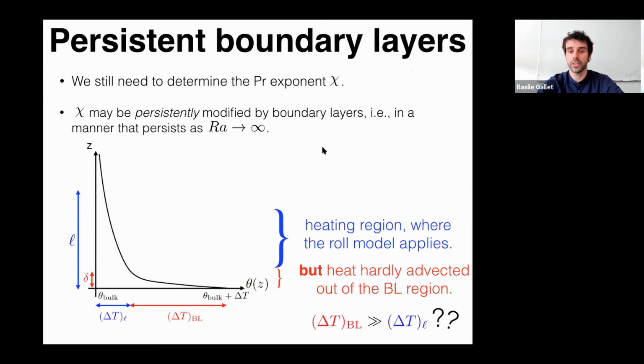However, this is still a real experimental tank, so we have a no-slip boundary condition at the bottom, and so there will be a boundary layer for the temperature field near the bottom. There will be a boundary layer correction to the temperature field associated with this boundary layer.